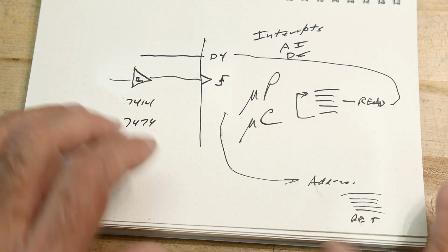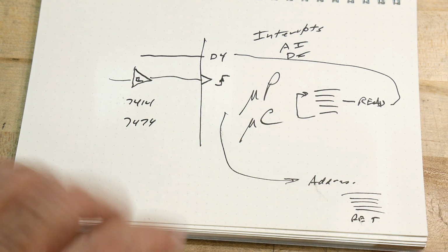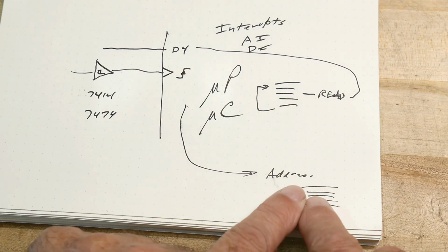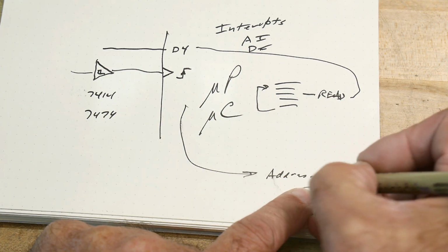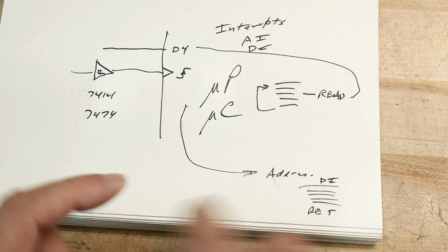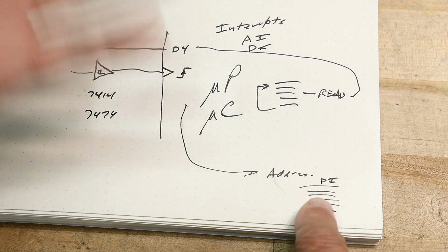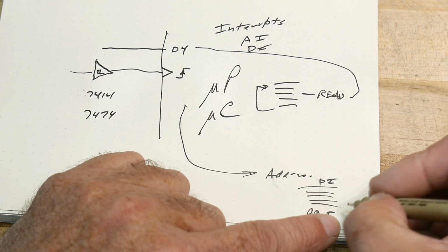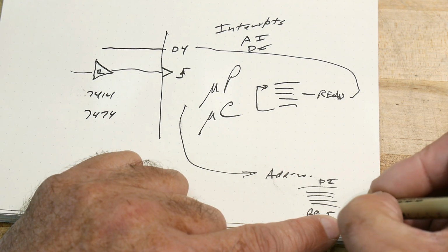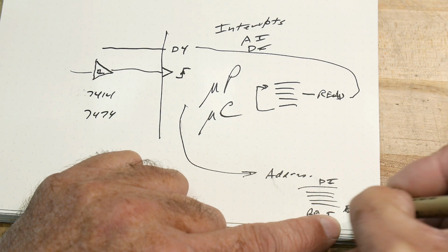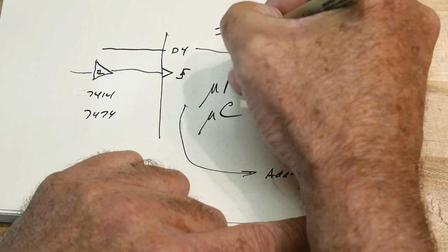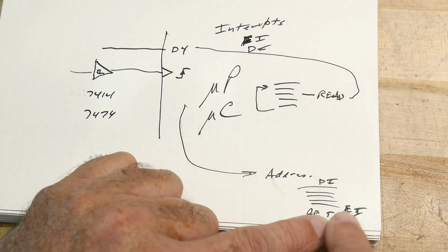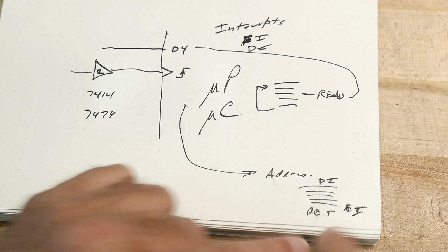A lot of times you don't want to get an interrupt on top of an interrupt. So when you get an interrupt and come down here, the very first thing you do is disable interrupts, because you don't want this to get interrupted by somebody else. You execute this, and the very last thing before you return, you enable interrupts and go back to what you were doing.